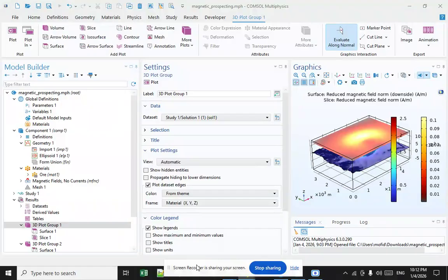The grain size of the magnetite and its degree of commingling with the silica groundmass determine the grain size to which the rock must be comminuted to enable efficient magnetic separation to provide a high-purity magnetite concentrate. This determines the energy inputs required to run a milling operation.